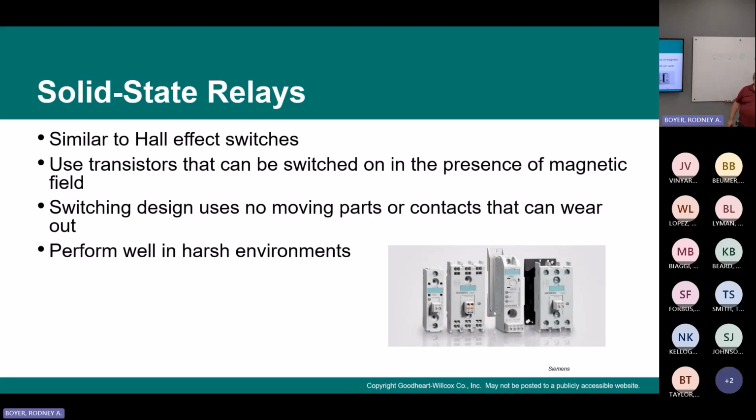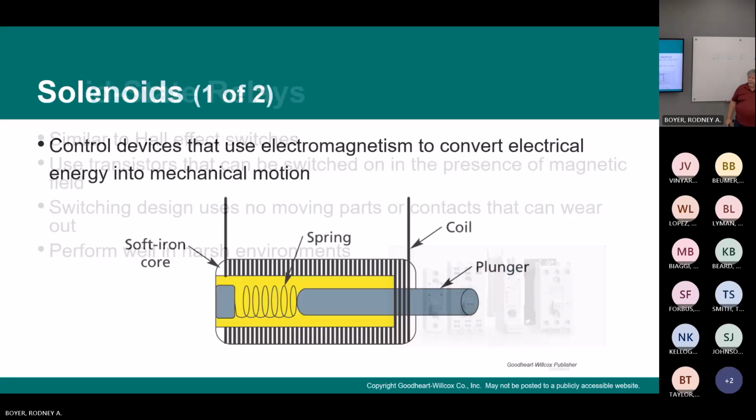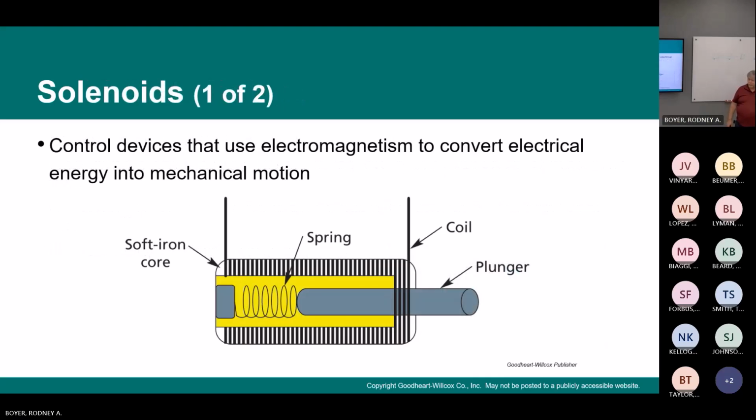Regular relay, whenever you de-energize the coil, a spring pulls the contact back apart. Solid state relay, once you close it, if there's nothing on there to dissipate the energy, it'll just continue to conduct. So you can have voltage present on the output terminal even after the coil is de-energized. Be very careful with them.